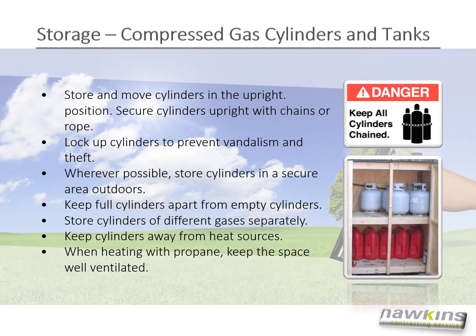When storing compressed gas cylinders in tanks, store and move cylinders in the upright position. Secure cylinders upright with chains or rope. Lock up cylinders to prevent vandalism and theft. Wherever possible, store cylinders in a secure area outdoors. Keep full cylinders apart from empty cylinders. Store cylinders of different gases separately, and keep cylinders away from heat sources. When heating with propane, keep the space well ventilated.